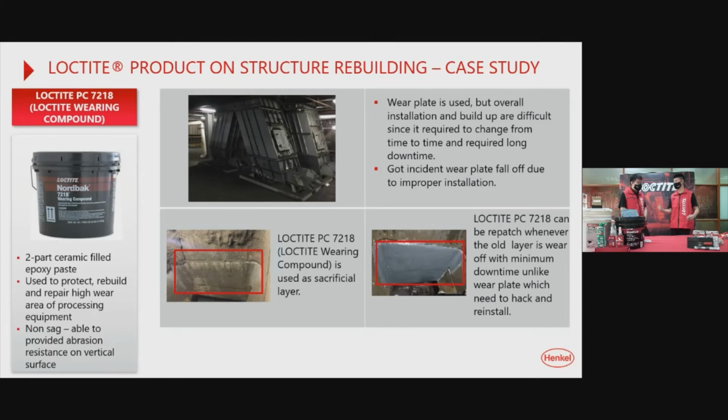And another thing is, whenever we do installation of these wearing plates, when we purchase, it's actually in the default size. So before that, we need to cut according to our equipment size so that it can fit accordingly. It's one extra step. Yes. Then you need to do some welding, all this. But using our wearing compound, you actually can eliminate that. You just find someone, just mix according to the mixing ratio, then you can patch whatever directly.